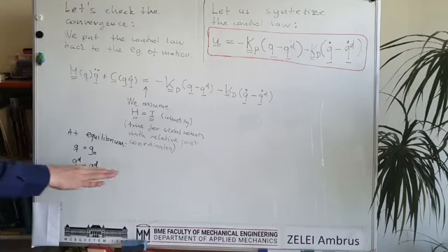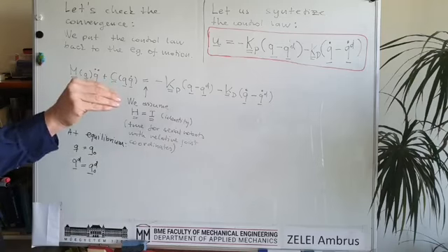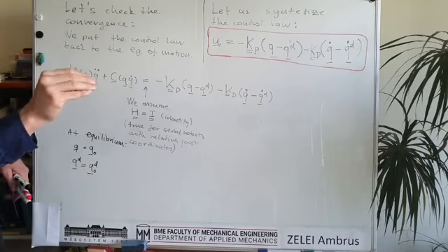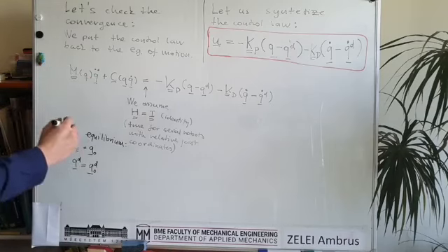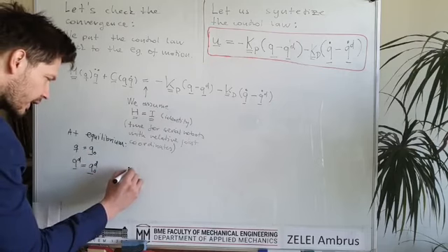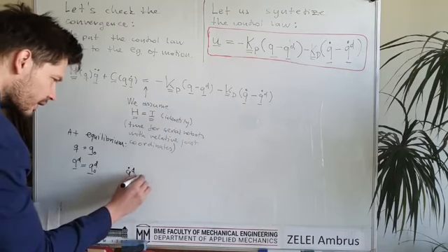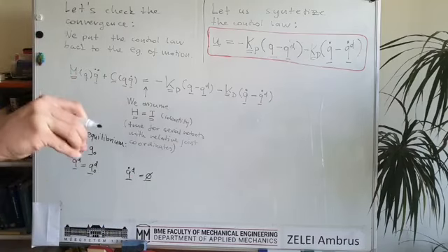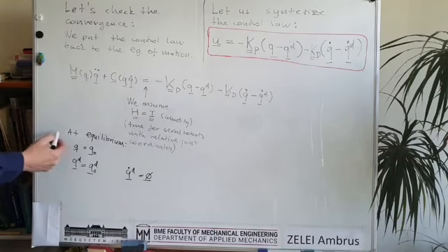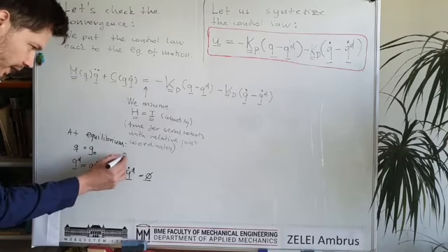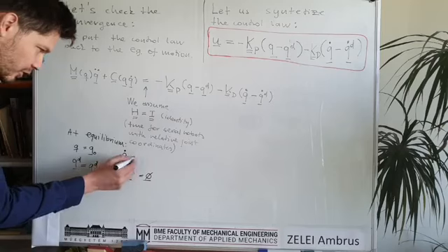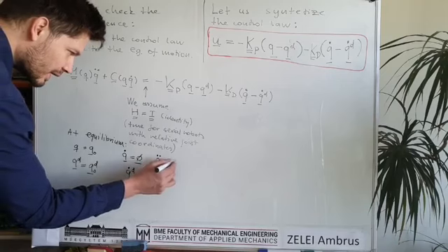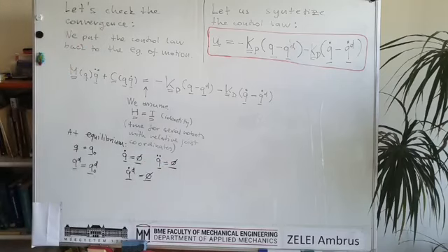So the task of the robot is just to keep itself at a constant, time invariant desired position, okay? Which means that there are no derivatives for the desired joint position. Okay, so there is no desired motion, just a static position. And we are in an equilibrium, so we also have zero speed for the joint velocities and zero acceleration for the joint accelerations. Okay, so everything is zero.